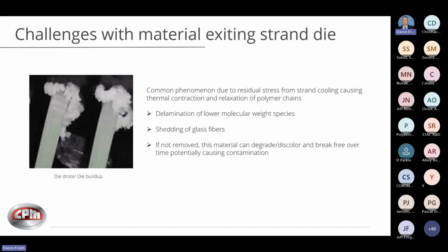Just note that over time, if this buildup is significant enough and sits against that die plate, it can be heated long enough that it starts discoloring, and eventually can break off and be carried in toward the pelletizer and become a contamination.